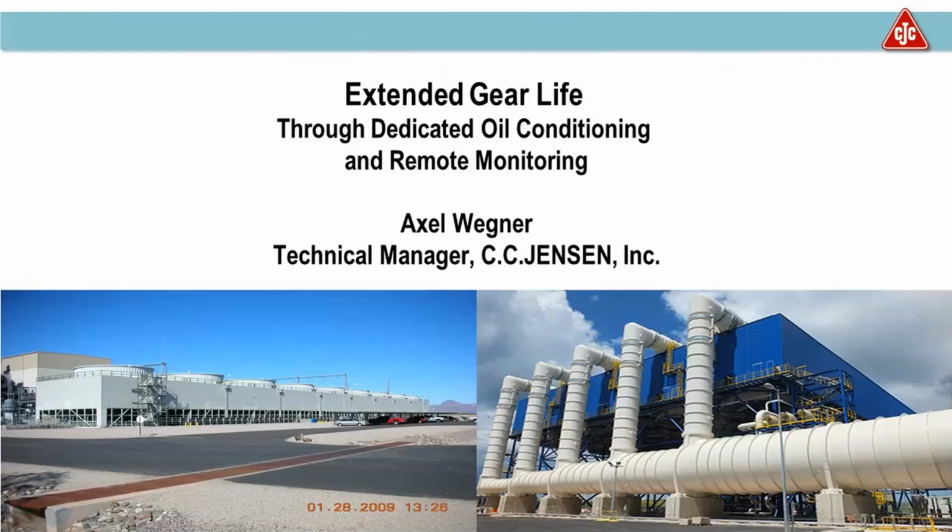throughout the whole life cycle of the gearbox and not just maybe for the first 6 weeks or a week or so. Yeah, and when you look at new oil, the average cleanliness of fresh oil is not even suitable for most applications. It's usually an 18, 16, 14. So that would typically require it to be filtered into the gearbox.